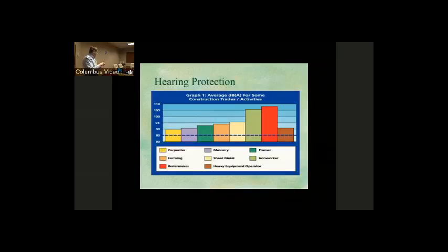Here is an example of noise exposure. Right now, we don't have any areas within any of our operations that we know of that exceed the OSHA standard of 90 dBA over an 8-hour time-weighted average. We do have some operations that have high exposure short-term, so we're not making hearing protection mandatory. It is available to you, especially for short-term operations. It's a good idea to get the hearing protection.